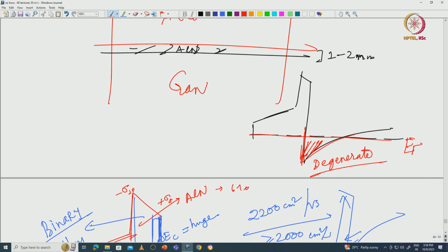At very low temperature, at cryogenic temperature like 4 Kelvin, millikelvin, your AlN GaN Hemt will have very high charge density and very high mobility. So, your current density will be much better at lower temperature than at room temperature. Okay, that is a very good beauty. So, you can use gallium nitride devices for cryogenic application, whether it is RF or power switching. Okay, that is a very interesting point. You should know that 2D density does not change with temperature.